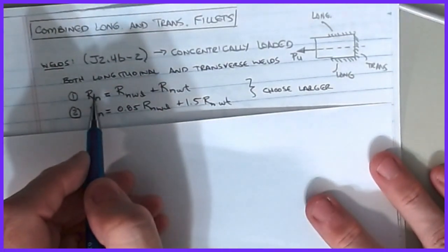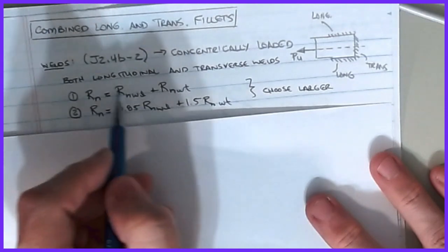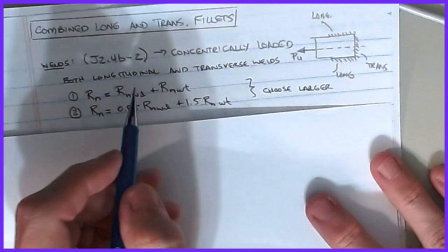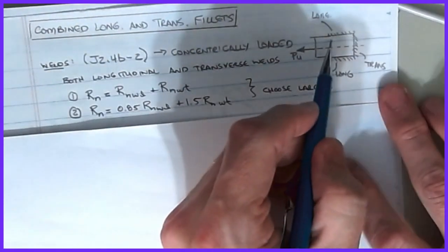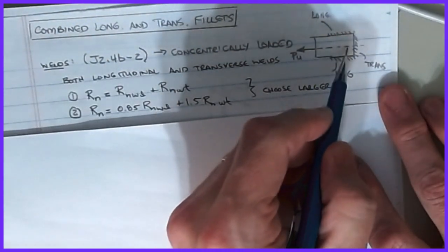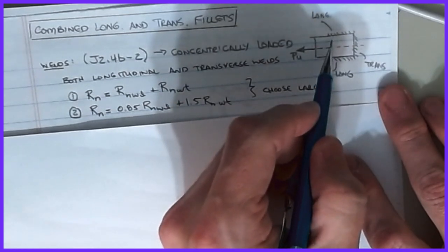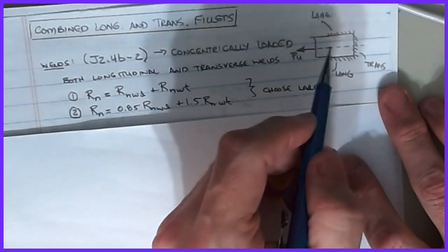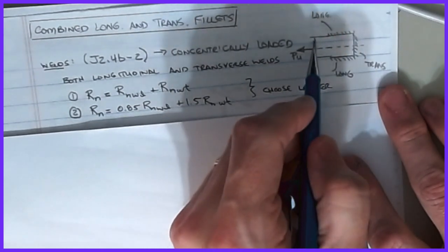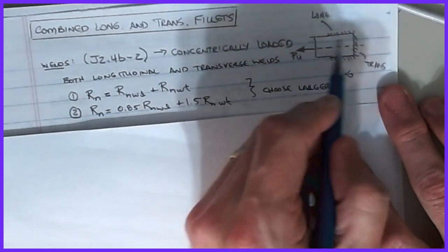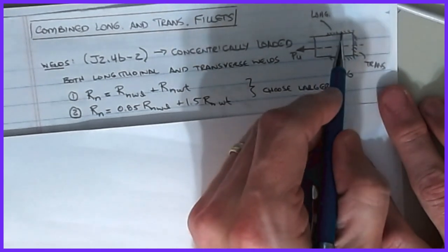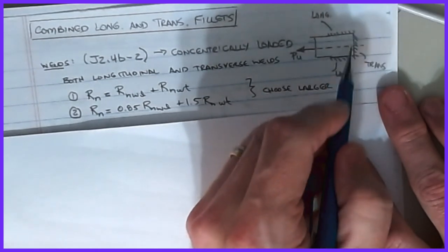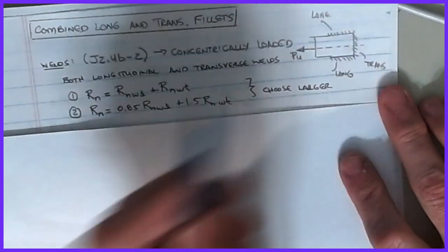And we could do it the classical way of just taking the capacity of all the longitudinal welds and adding it to the capacity of the transverse weld. That's what these two quantities are. But there's also an interaction that happens as stresses get distributed a little unusually in this. Because I've got the side tied off and the end tied off, this little corner back here may not be doing as much work as we had hoped. Or, if this is my stress, the majority of the stress is wanting to go into the transverse weld as opposed to flaring out and going up to the longitudinal. So instead of being a uniform stress across this, it's actually kind of piled up in the middle.